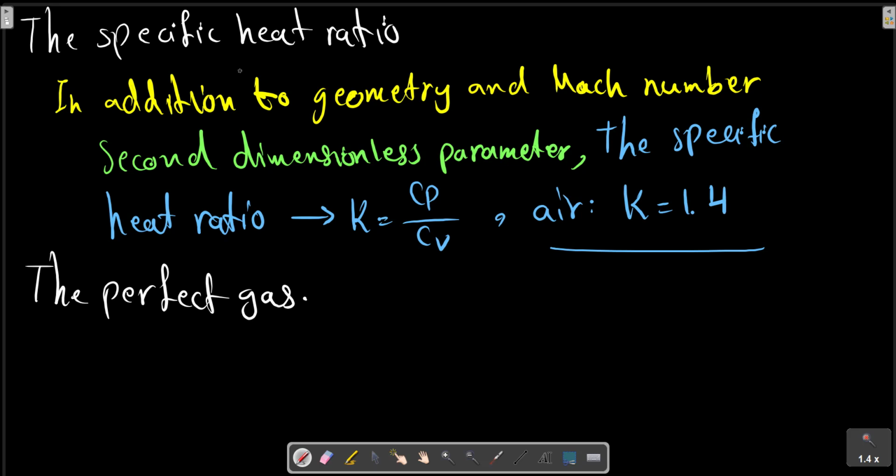In principle, compressible flow calculations can be made for any fluid equation of state, and we shall assign problems involving the steam tables, the gas tables, and liquids, but in fact most elementary treatments are confined to the perfect gas with a constant specific heat ratio,